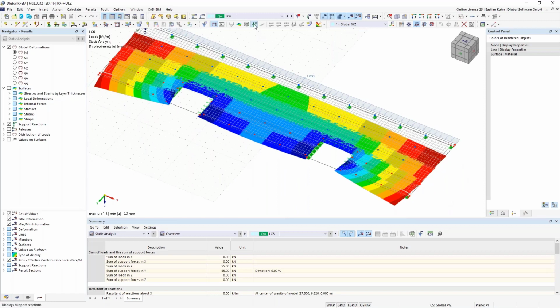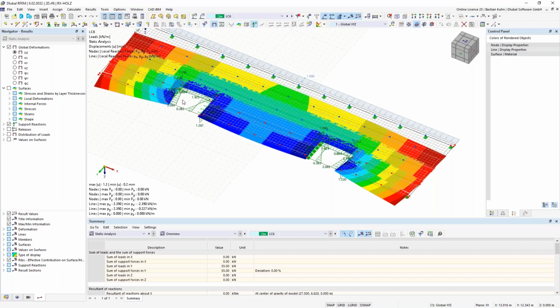When we then look at the supports, you see that you have the support forces. You need to connect via connectors to the concrete kernel of your structure. Also, the plates inside each other need to be connected, or as we defined the slip, they are connected via screws or something like this.